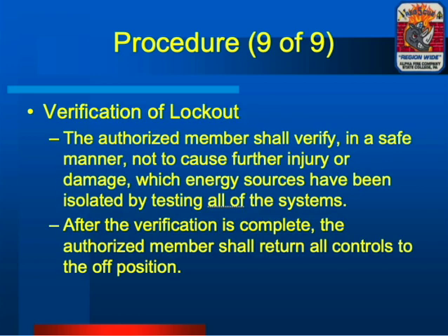Moving from there, we're going to verify that the machine has been locked out. Again, this goes back to, do you push the button one more time? That is really going to be a decision by the person that is conducting the lockout tagout operation. I sometimes question pushing the start button one more time or operating a power lever. Do I really want to add more injury to the person? One of the things you could use is an electrical testing device. So you turn the power off, you lock the switch out, and then you check it one more time with some sort of electrical tester to verify that yes, the power has been turned off.